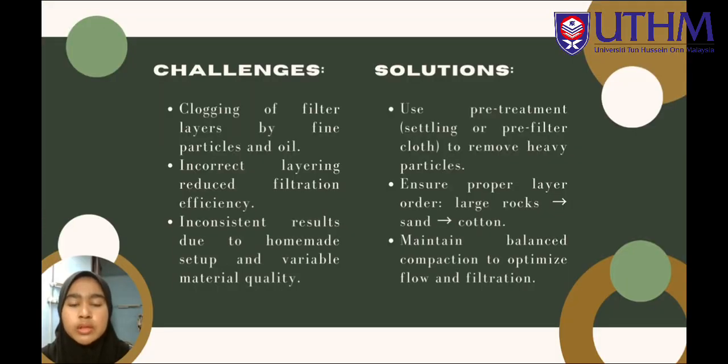Lastly, I will be presenting our group reflection based on the challenges we faced and the results we observed during the wastewater treatment project. Throughout the filtration process, using a bottle filled with cotton, sand and rocks, we encountered several challenges. The most common issue was clogging, especially when treating water that contained a lot of fine particles and oil. Another issue was improper layering of the filtration materials, which caused the water to pass either too quickly or unevenly. We also found that sourcing clean materials like fine sand and cotton was difficult. These factors affected the consistency of our filtration results, especially since we used a homemade setup.